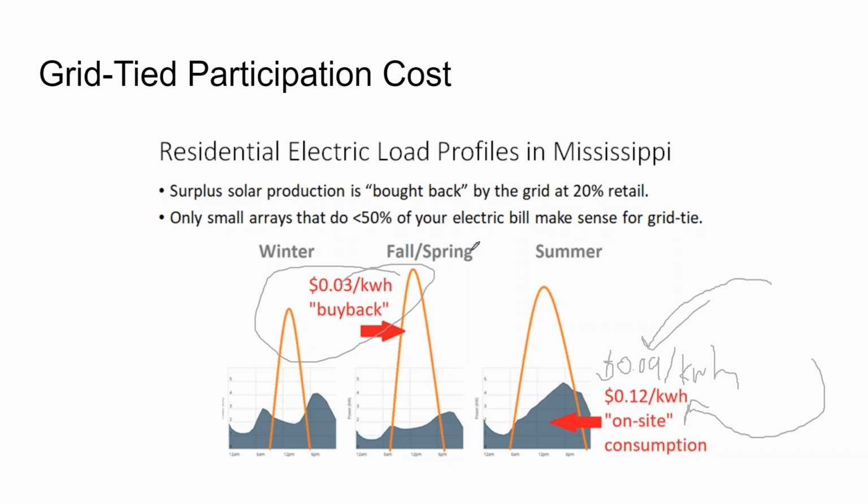If I had done a 7 kilowatt array instead of a 14 kilowatt array, I would have bid a $3 a watt installation price. And so by doubling the project size, I can give them a unit price discount of about 33%. So even at the residential level, economies of scale, doing larger projects, trying to hit that 100% offset mark is going to be a way to lower the installation per watt price of the project.